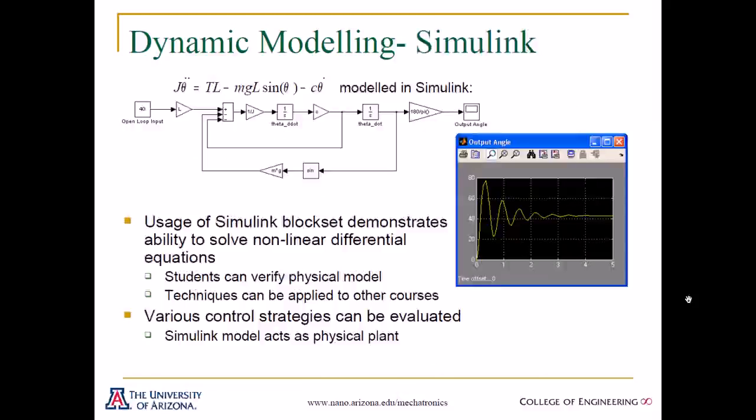Before asking the students to develop a real-time Windows target interface, we teach them how to use Simulink. For this purpose, we provide them with sample values of the parameters of the system, and we ask them to build a block diagram representation of the equation of motion. You could see an example of this block diagram here.